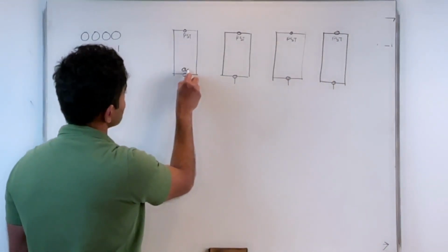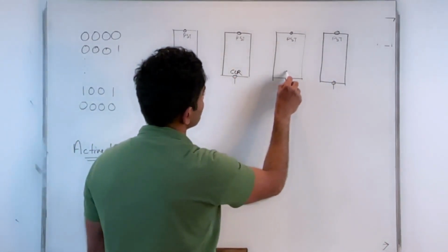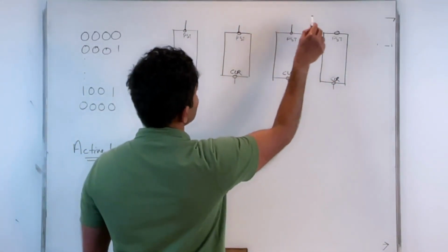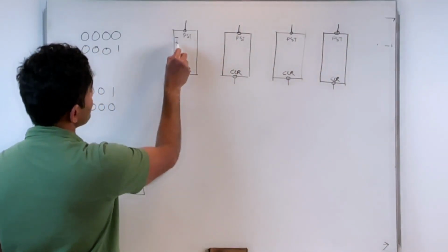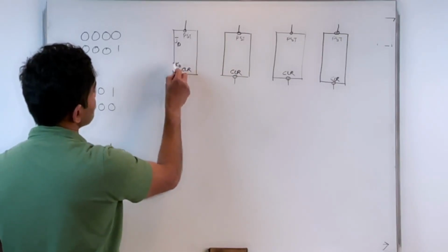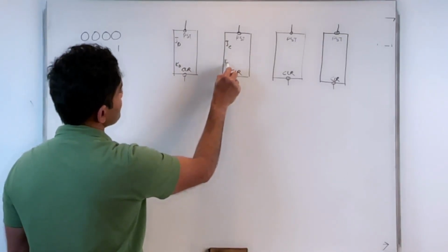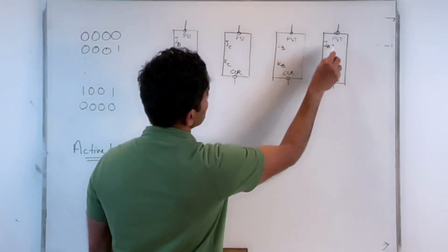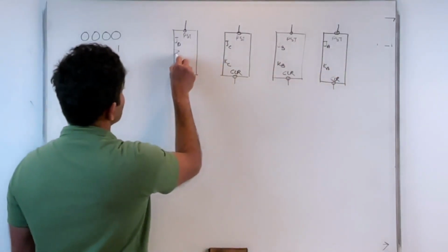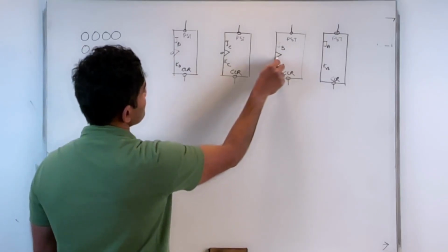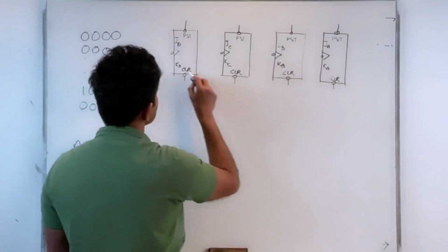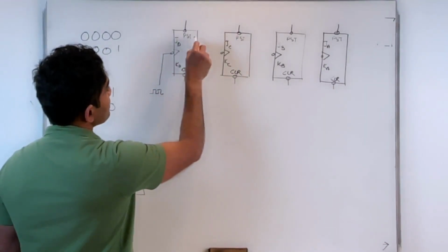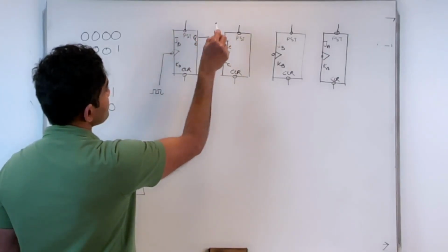and these are my clear inputs. And I have to configure each of my flip-flops. This is my JD, KD, JC, KC, JB, KB, and JA, KA. These are all negative edge triggered flip-flops. That's the master clock. And that's my Q output, QD, applied as a clock.